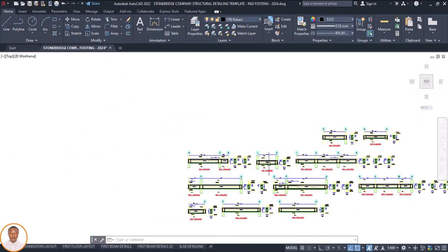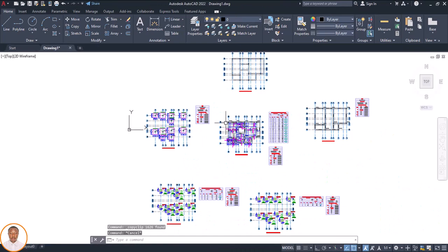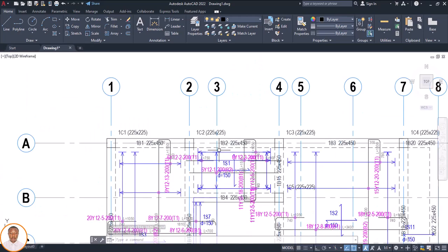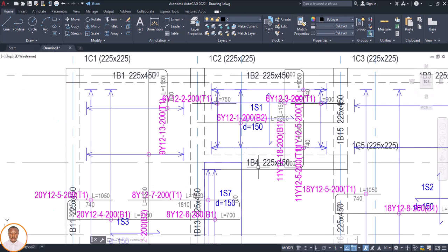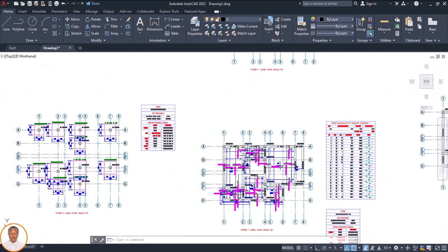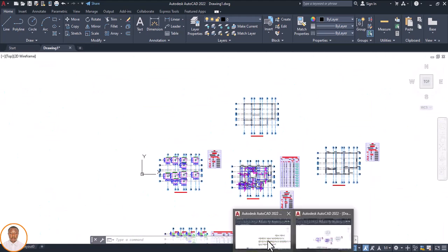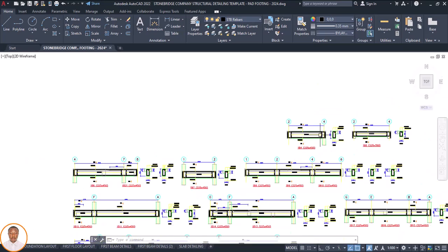And in order not to be confused, you can also come to this place. Let me show you something here. You can see this is 1, 2, 3, 4. This one here is beam 4. Is that okay? Since this is beam 4, I'll just come to this place and look for this beam 4. You can see the beam 4 here. Now, how I arranged this one, how I got this out so that they are all arranged like this, is in my Prota detail. That's why I brought this one out like this.